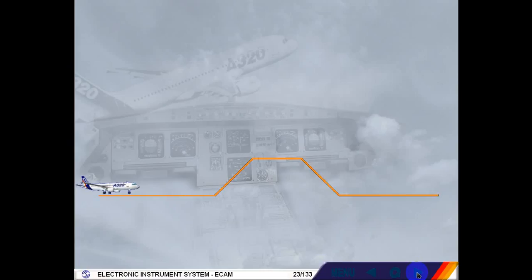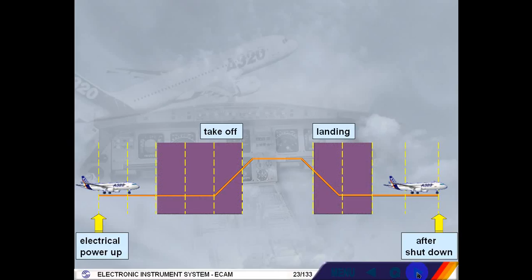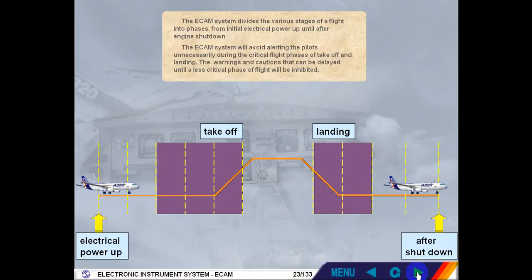The ECAM system divides the various stages of a flight into phases, from initial electrical power up until after engine shutdown. The ECAM system will avoid alerting the pilots unnecessarily during the critical flight phases of takeoff and landing. The warnings and cautions that can be delayed until a less critical phase of flight will be inhibited.